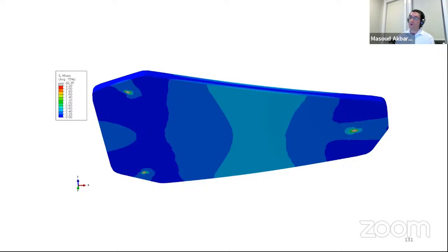If we wanted to design this glass as a monolithic piece, the thickness of the glass had to be around 2.5 centimeters, or 1 inch. If you calculate the weight of the glass, it would be around 500 kilograms, right? So 1,000 pounds. This doesn't really make sense for a piece of furniture, because then you need a crane to move your piece of glass and install it at home.